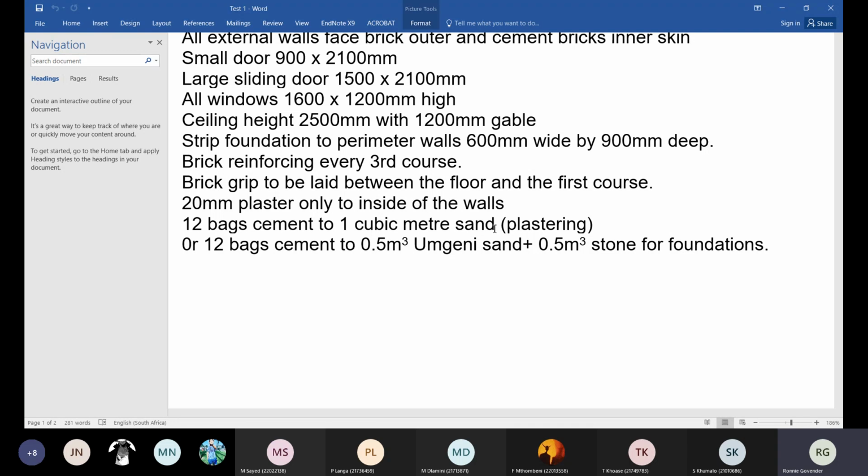That's how we remembered it, because we needed to work on a log figure table where the average one was about 9 figures that you needed to work off. And the other thing is a pocket of cement, because cement comes standard at 50 kgs, from the time I remember. I think when I was a little boy, it always came at 50 kgs. And 1 pocket of cement is 0.0347 cubic meters. Those are the 2 magic numbers that you should remember, every student doing civil engineering. Right, now, there we go.